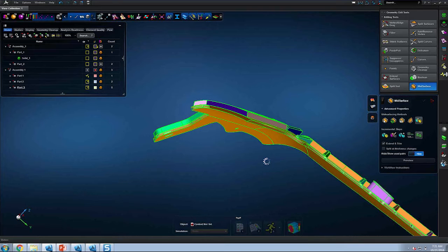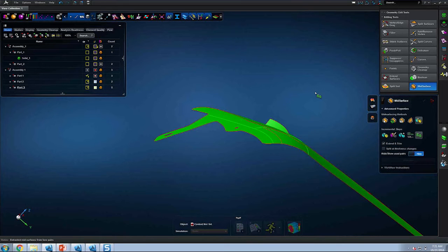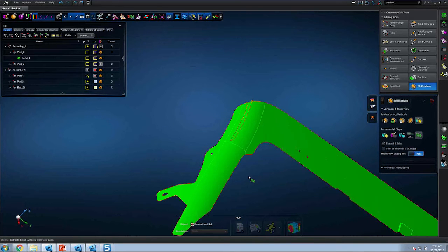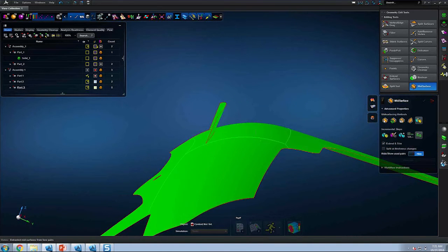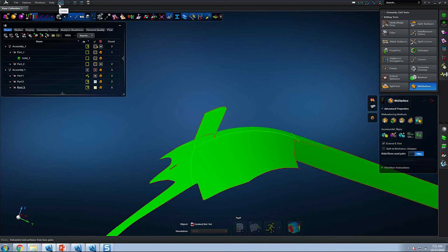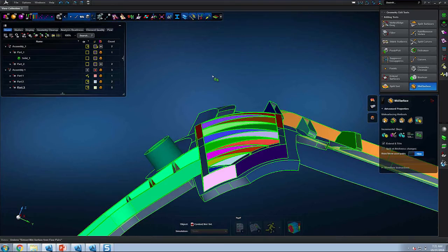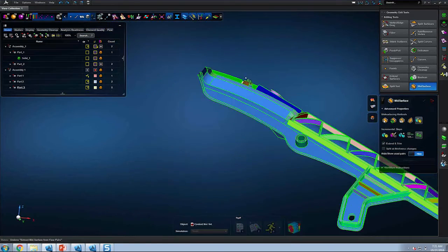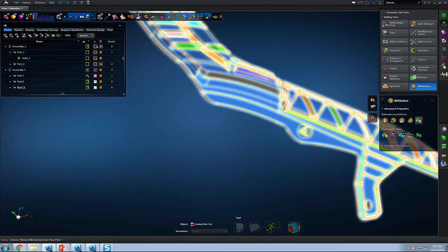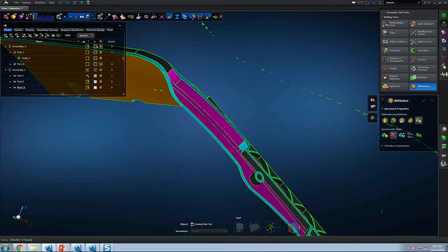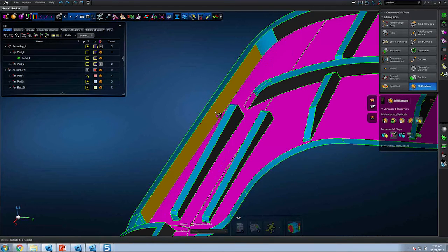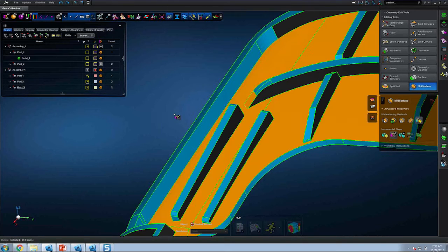By doing this, it's going to reveal any issues with the geometry up front. This can let me then take action on how to remedy this. So here are a few things that initially stand out. One, there's this almost unusual midsurface that was created here. Let's take a step back to a point where we did not create this midsurface geometry. Here we find out that this large color-coded pair at the bottom is actually using this rib as part of the pair. And what I can do, of course, is deselect that pair from the rest of the color-coded pair.